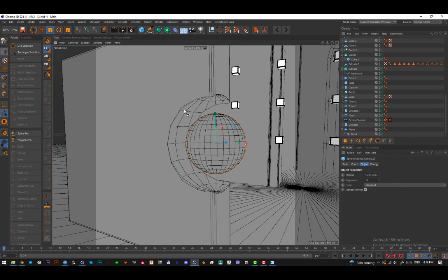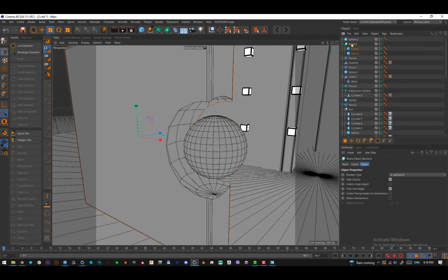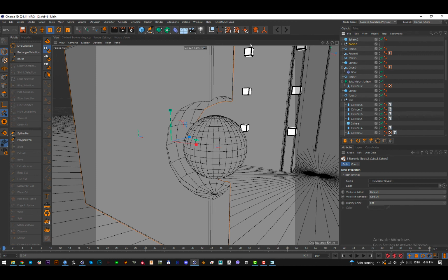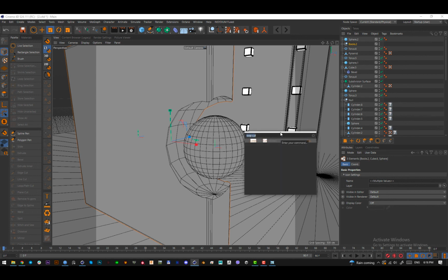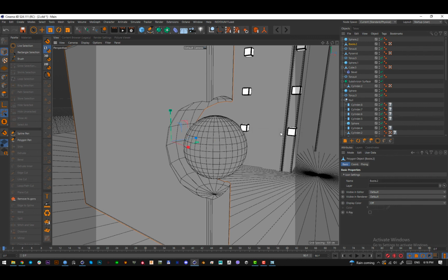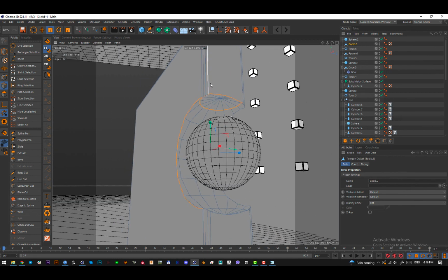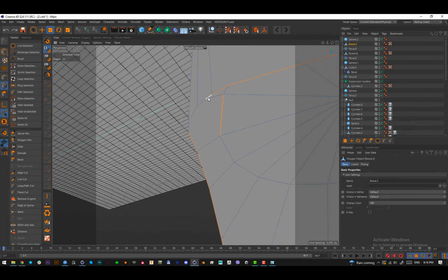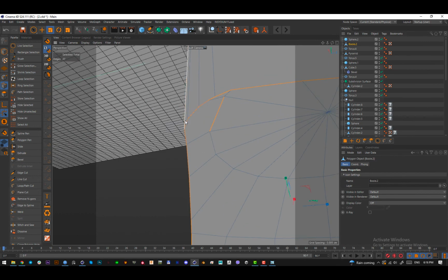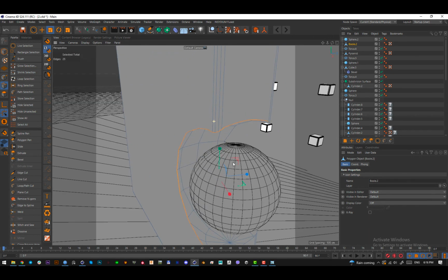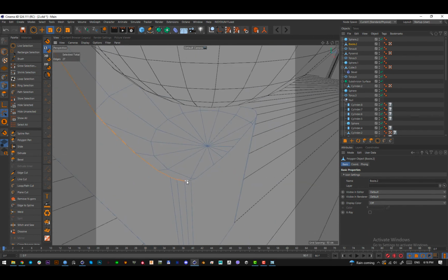Okay, we want to add some fillet to this shape here, so let's see. Press on the bool here, press C on your keyboard, use the mouse wheel button to select all of these and select connect objects plus delete. You can press Shift C on your keyboard to open this and press connect objects plus delete. Now go to the edge mode and double click this edge, double click this edge, double click these. Or you have to click them manually. Deselect the edges that you don't want.